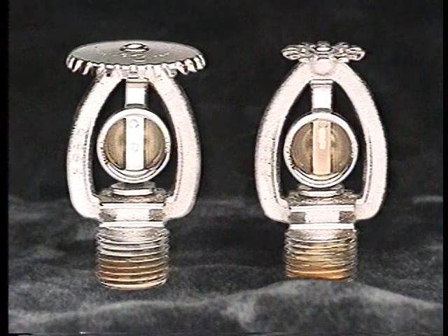There are also several types of sprinklers, each one designed to adapt to specific installation requirements. The spray sprinkler is the most typical sprinkler. It is the one upon which the requirements of the NFPA 13 are based. This type of sprinkler distributes 90% or more of the water discharge downward.